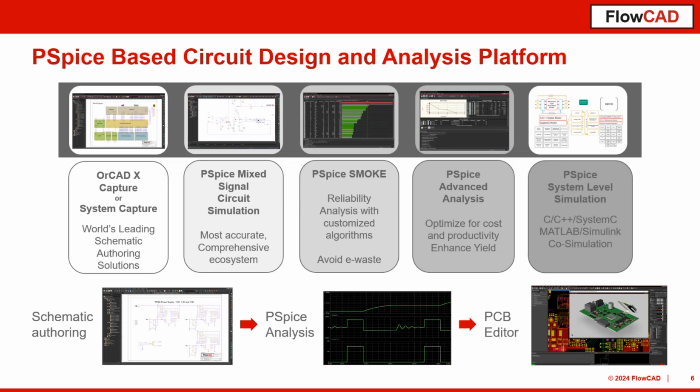That might be interesting if you have to analyze electromechanical systems, where you have the electrical implementation in PSpice and the mechanical behavior in MATLAB Simulink. You can link these two simulations and run them at once. Or you may have a very complex control regulation structure created in Simulink, and you can make use of that as well.